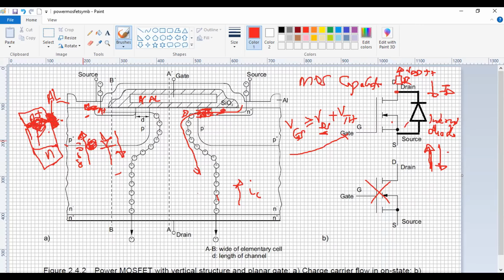Then, as you can see, this is a bipolar device. Remember, with bipolar devices where you have holes and electrons, the switching is slower. It has a lower speed, which means that switching this body diode on and off would take a bit longer. If you really wanted to, you could install an external so-called fast recovery diode, but that would have to be a device external to your actual device.